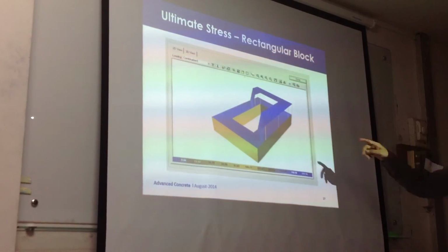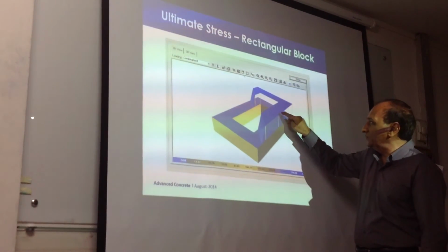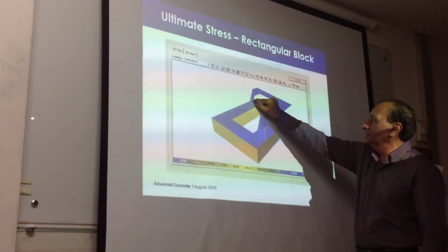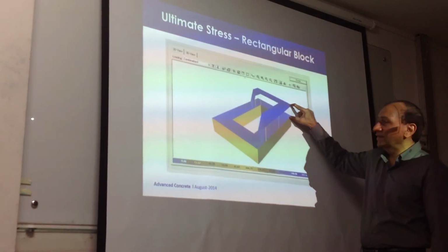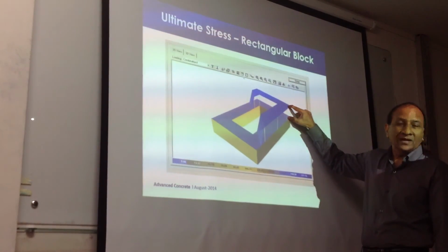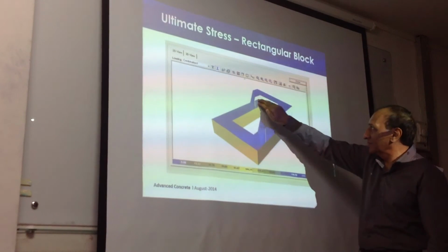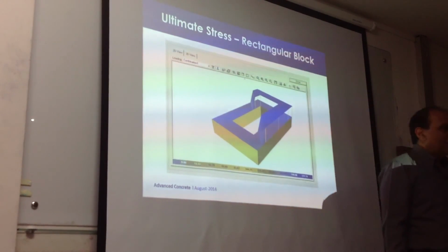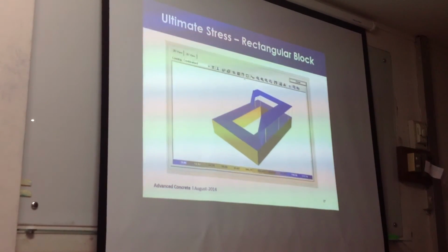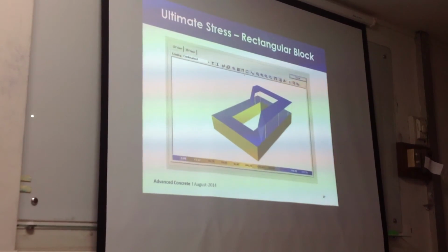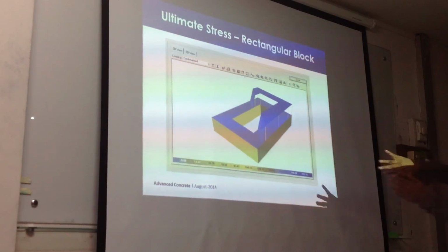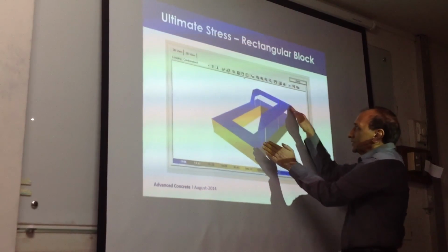Now because it is flat, it's easy for me to calculate that area multiplied by this height, and I can calculate the total. But if this was a curve, then I will be in big trouble, because then I cannot easily calculate the force component. I have to really integrate that stress over that area, and that is difficult, because this surface is actually going to be like this, because there's a stress-strain curve.